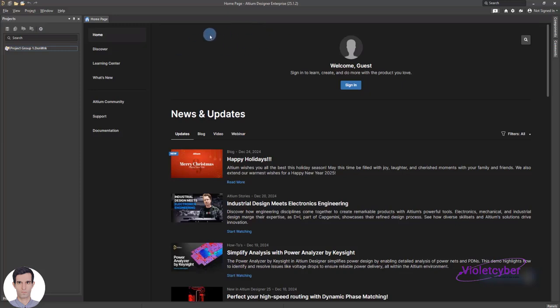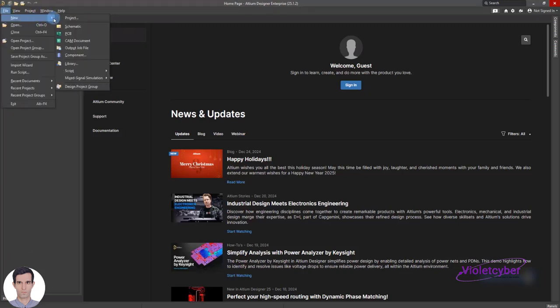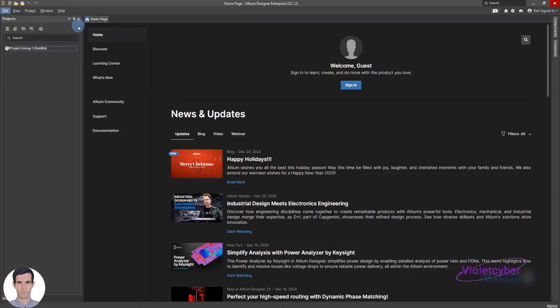Now in this session you will use another tool. We want to work on it. So in order for us to be able to implement a PCB of a circuit in Altium Designer, we need to create a new project, which I will create like this here. We click on File, and then here the first option we need to select is schematic. We select schematic and click on it because we must definitely make the circuit schematic.